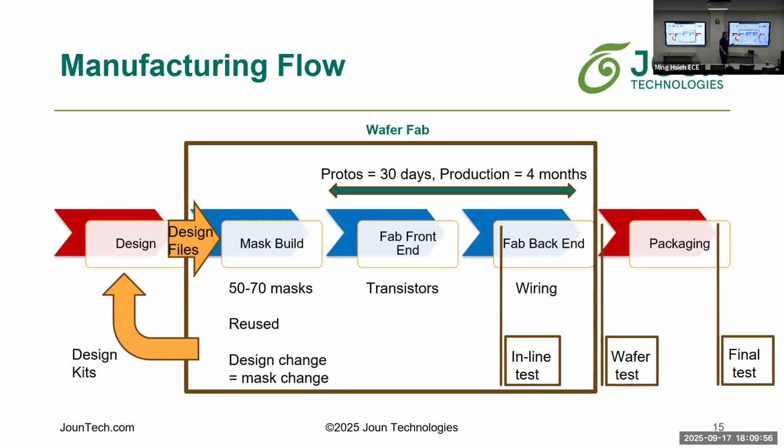But the thing is, until you get to the just-start of the fab back end, when you put down the first layer of wiring and connectivity, you really don't know what you built, if it is functioning well or not, right? So as soon as you get into the very early part of the back end and put down the first level of wiring, it gives you the first opportunity to do an inline test. Basically it allows you to test some of the switches or transistors down there to ensure that you haven't messed something up. But this could be 2 or 3 months in. And if something is messed up, this can be a big problem.